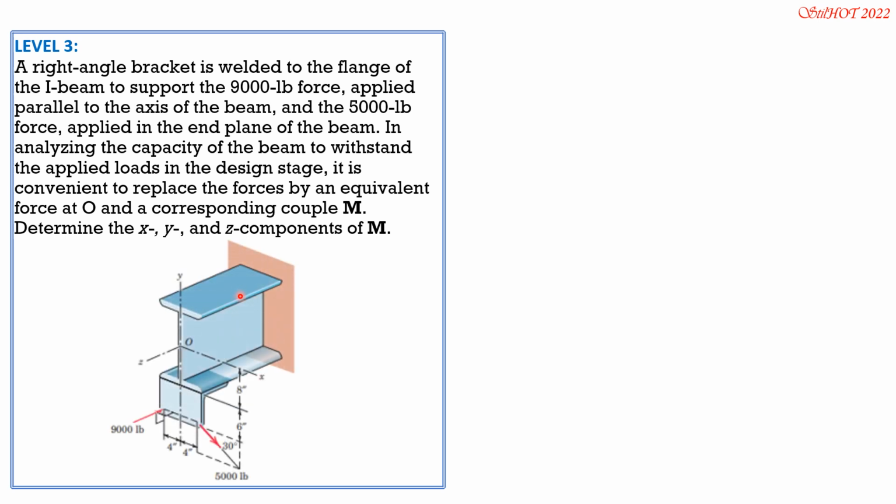So in this case, there's no need to apply vector approach. We just use scalar approach and the right thumb rule. So let us compute the components of this 5,000 pound force. The components are rightward, so 5,000 cosine 30, and downward along Y, 5,000 sine 30. So the components are, I just write it right away, 5,000 cosine 30 is 4,330 pounds rightward, and 5,000 sine of 30, this one, is 2,500.